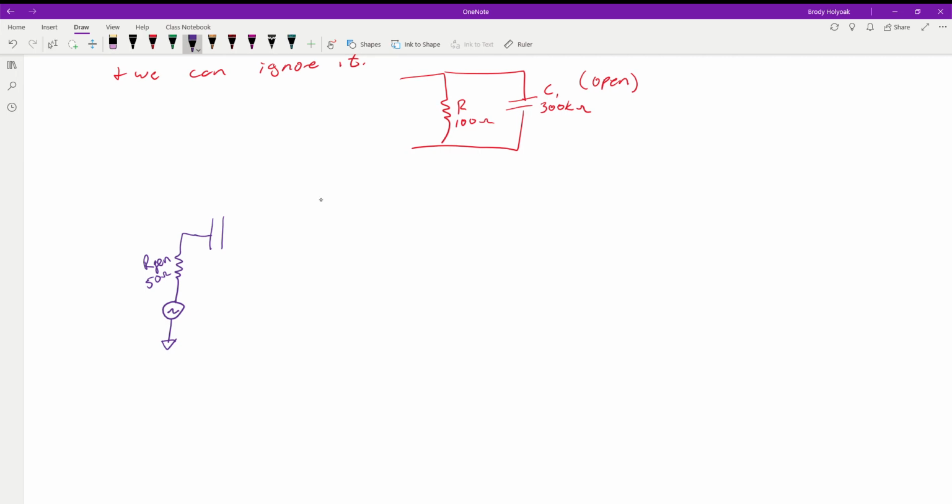So anyways, we have our generator. We come in through capacitor 1, which is a coupling capacitor. We go from that into R1. And then from here we branch. This is where we're going to bring in our DC portion. So we have R2, we have R3, and then up here, we're going to add in our DC voltage coming in. We're going to split it up between these resistors. Then we come back down here to our junction between R1, R2, and R3.